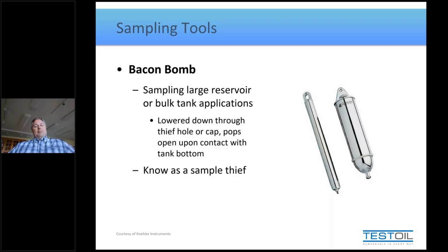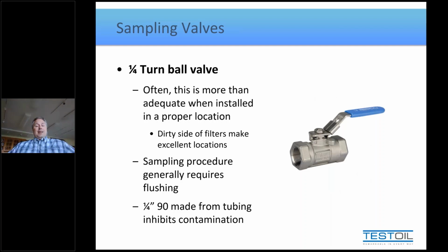Take note. But the one thing I'd tell you about all of these sample tools is they're all designed to do a particular task either simpler or more conveniently than trying to do it through openings, hatches, dipsticks, whatnot. But the one thing I would never take away from you is to say that a quarter-turn ball valve is not a proper sample valve. It is. It works just fine. It's quick to open, quick to close. It's easy to adjust the flow. It's very easy to flush it. It works very, very well.